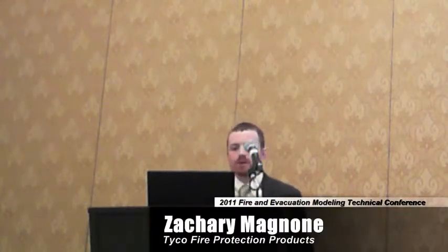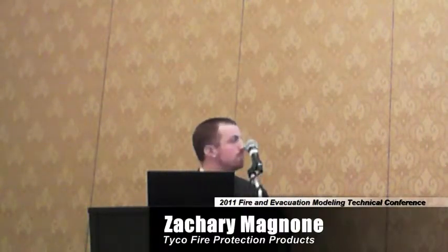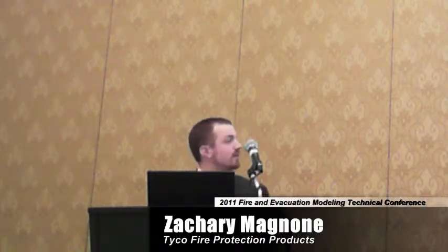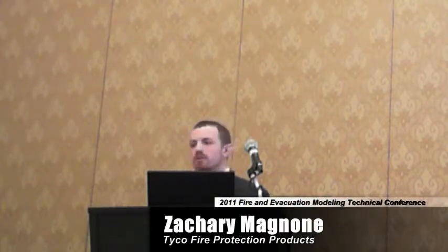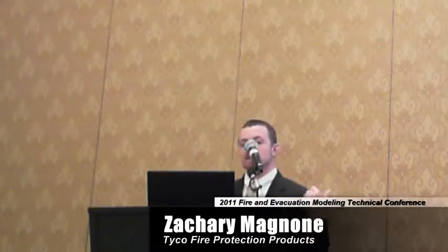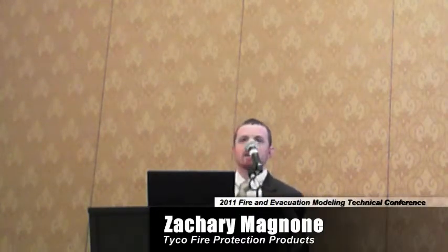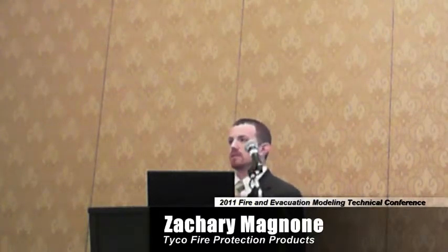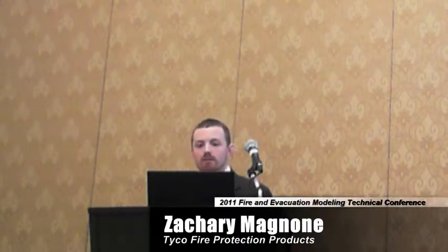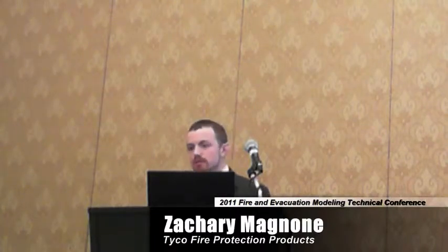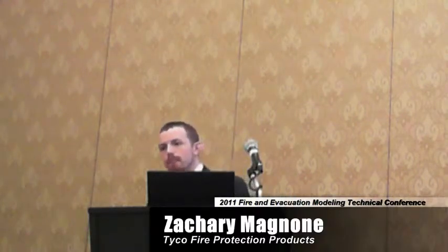Yeah, well, in the real world, you do have some high spots because of frame arm interactions, for instance, and you also have the influence of slots and tines plus some shadowing from the frame arm. So that's something that you could account for. In this case, we were just looking at having a spray that would give us the right sort of gas phase cooling and impact. There's nothing saying that you could not use, for instance, a table and create some simple regions and use the same type of analysis to get a little bit more complex spray. Yeah, there's going to be more variables you have to play with.